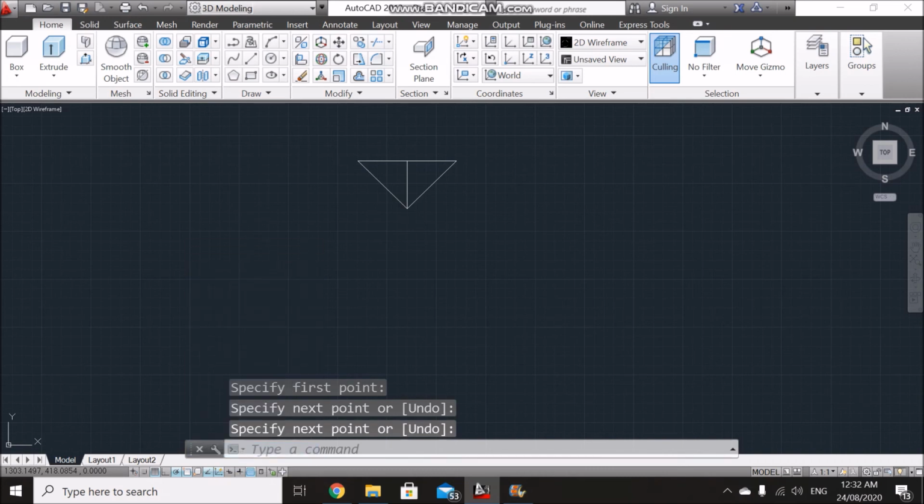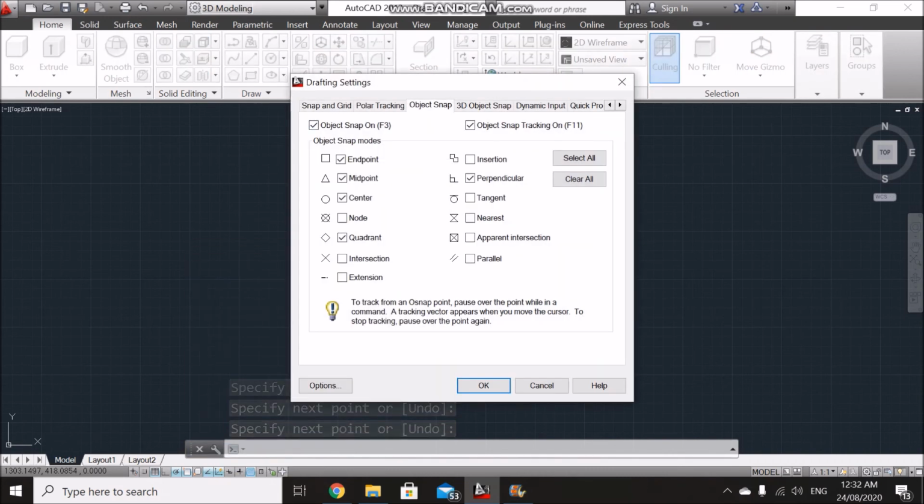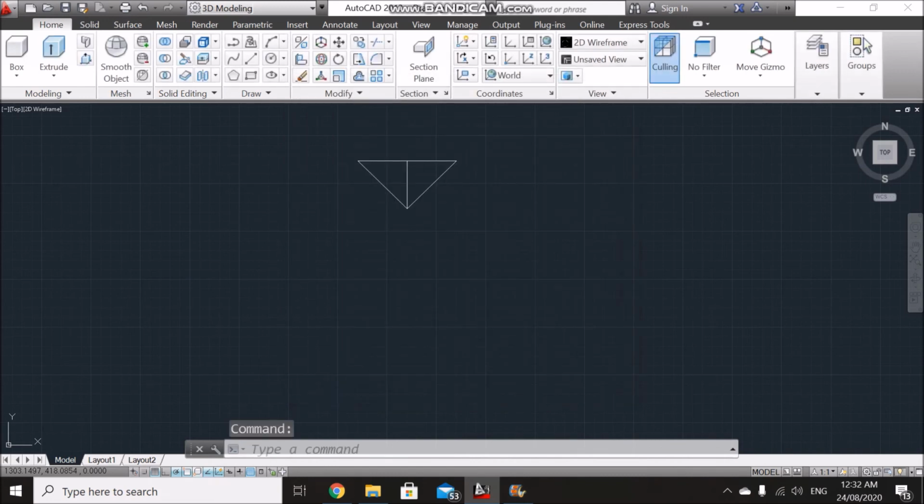Right click, settings, and then you can choose whichever object snap modes you want to enable. And then of course we have several commands down here, but I won't be explaining those extra commands or functions that are disabled. Next we have object snap tracking. Of course, if polar tracking is enabled, you also need to enable this, but by default it's already enabled. We have allow, disallow dynamic UCS. That's the view for your objects or for your drawing space. And then we have show, hide, transparency.